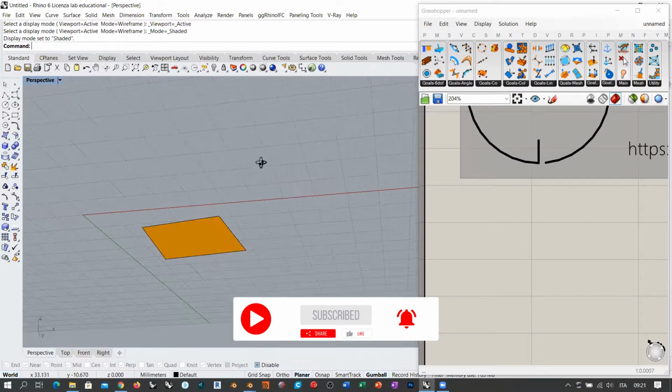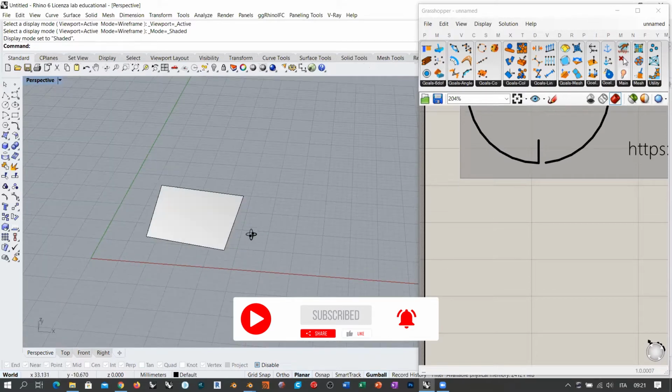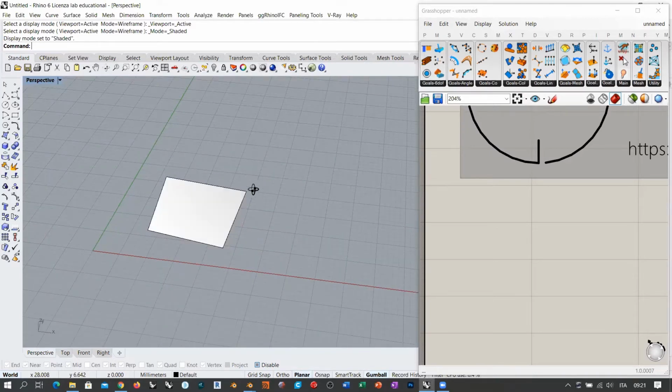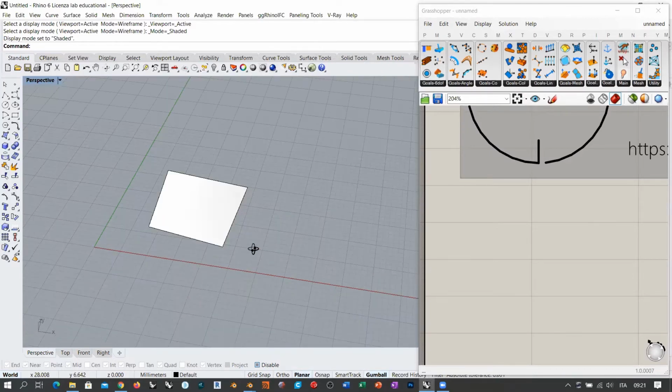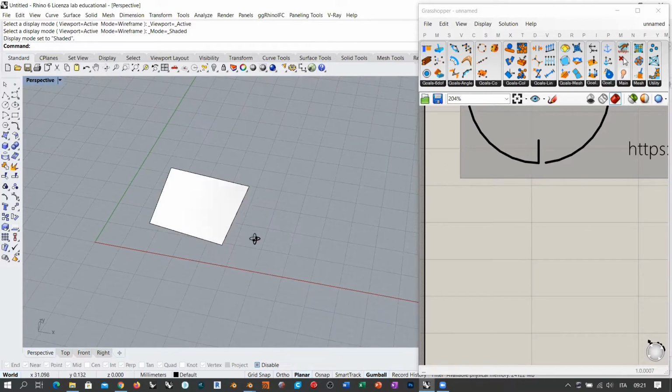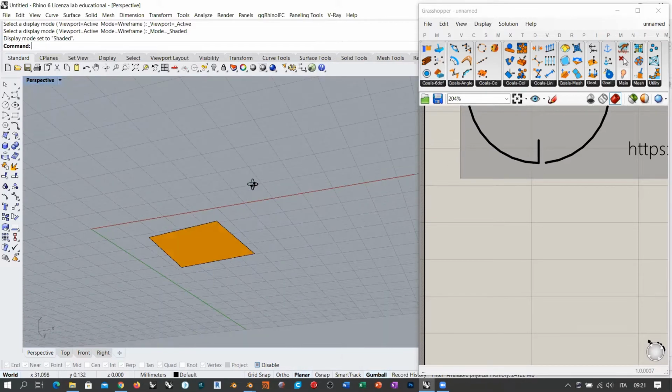This is a setting that we have in Rhino. You can decide to see all negative faces with a specific color. This is not the default in Rhino, but if you want this kind of appearance, because I think it's useful to understand the orientation of surfaces and meshes, especially if you are going to somehow bring this object to reality with some manufacturing process.